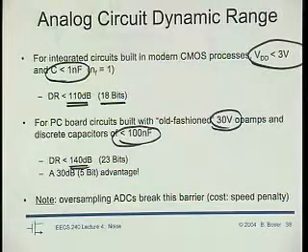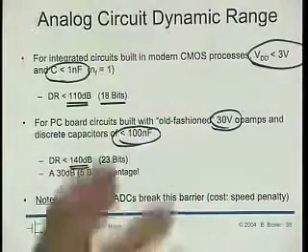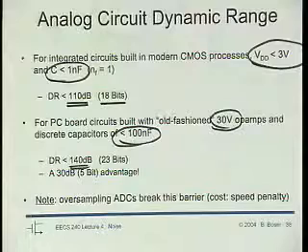So actually, I mean, everybody wants to integrate. Well, it's not always the best thing. If top signal to noise ratio matters, I'm going to buy one of these old-fashioned operational amplifiers from Burr-Brown or ADI or Linear Technology or so, right? Use a 30 volt supply, buy the biggest and best capacitor, and we're going to beat the IC design. Of course, it's going to be bigger and probably more expensive. It all depends what matters, right?